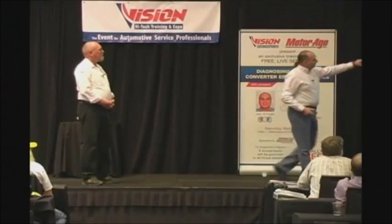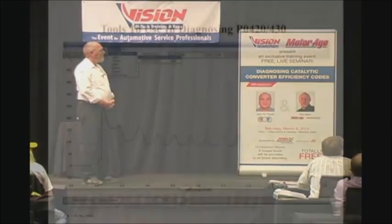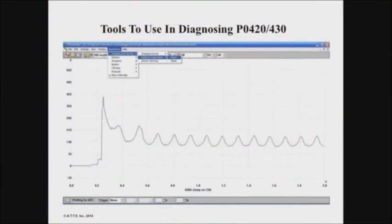Here's Pico. When I first crank it over, first the little hump for 0 amps, the little hump at about 50 amps, because each line going up is 100 amps. I get up to about 400 or so amps on the initial crank. And then you can see the little humps on the bottom at approximately 150, 160 amps. But they're even. If they weren't even, I got a cylinder problem.